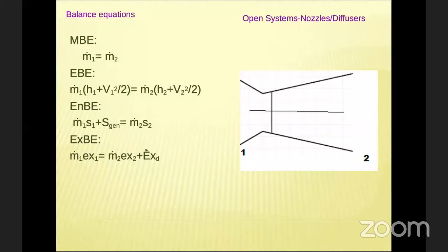So we are eliminating all the heat transfer and work transfer terms because a nozzle is only an energy transformation device, not an energy transfer device. We are not getting any shaft work. Okay, and the entropy balance. In a nozzle, definitely entropy will be there because enthalpy is there, flow energy is there. So m dot s1, that is the total entropy at inlet, plus because of this flow, entropy will be generated. In a nozzle, friction will always be there, so entropy will be generated. This is another reason for irreversibility in the process. This is equal to m dot into s2 final.